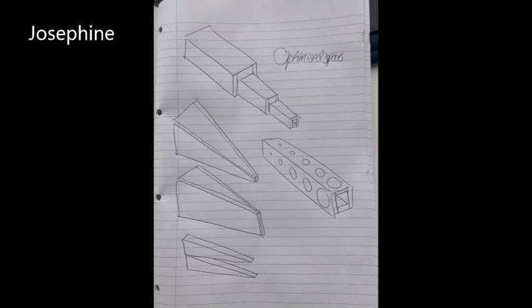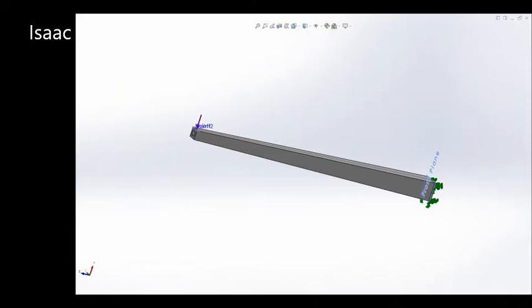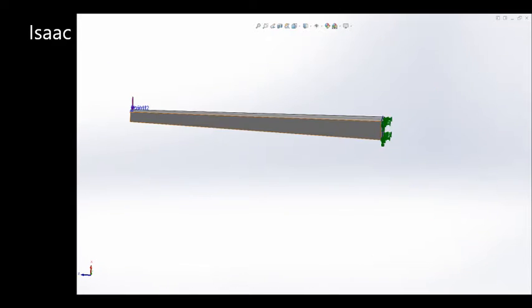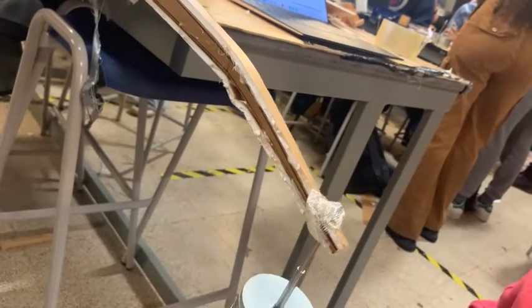Bending moment may be too large for certain parts. The wedge design was best as stress was highest at the tip and least likely to fail from compression at the root. It was theoretically supposed to fail closest to UTS of foam board under 20 newtons force.